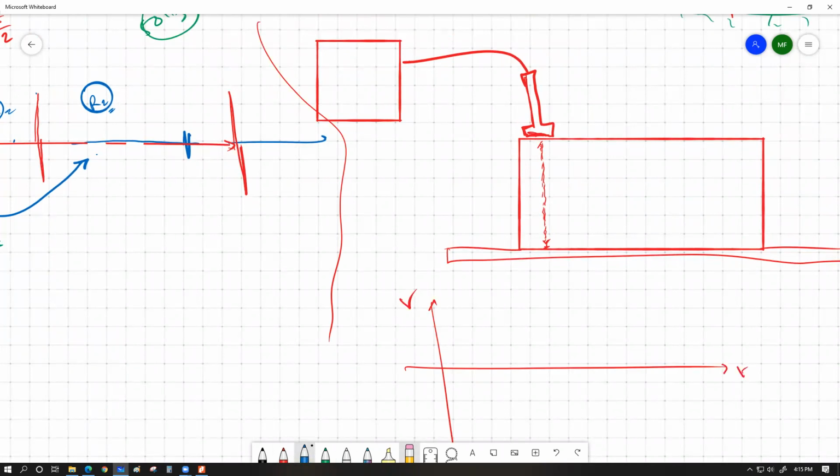Let's say for a good iron piece, this is our send pulse, and this is our reflection. I'm going to draw it 3 divisions apart, and let's say we send another send pulse after 2 more divisions. So we are sending the send pulses over here.